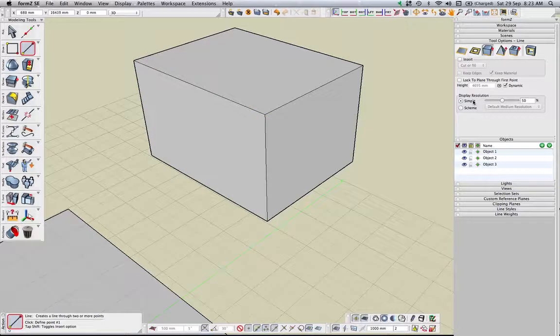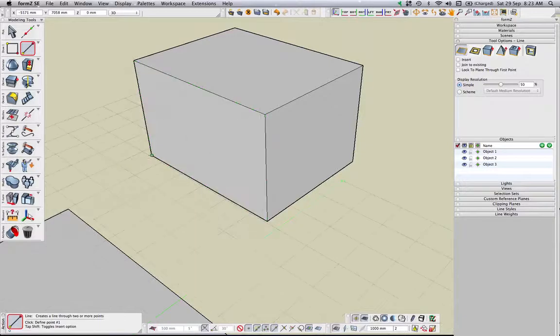Now notice over here it's quite important. As I'm drawing this line, you can see at the moment I'm in my 3D extrusion type tool. I just want to draw a simple line on this face. So I don't want to extrude this line. In other words, I'll change to just a 2D surface, and I'm drawing a simple 2D surface through here. And it's important at the moment, I want to show you, don't have this insert selected. We won't draw this line inserted into anything, and I'll just draw a line across this corner. Okay, and I made sure that the reference plane was correct through there.